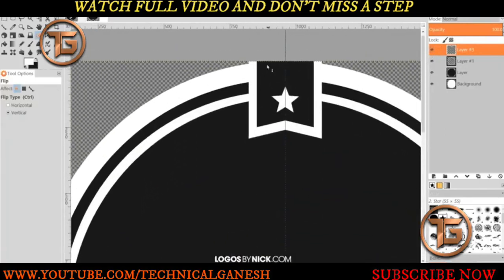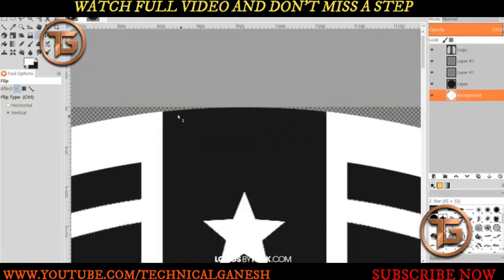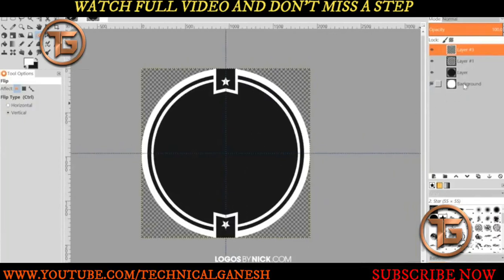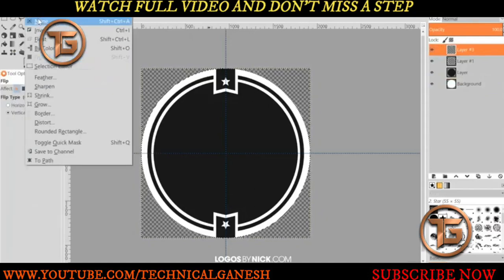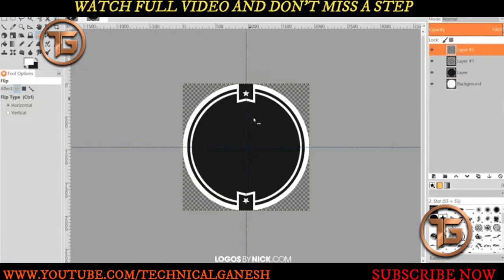And the final step for this segment right here would be to cut out this area that's protruding outside of the circle, because if you notice on the original logo, it's confined within the circle there. So in order to do that, let me zoom out. What I'm going to do is I'm going to click on our original layer down here, this white circle, the background layer, and I'll right-click that and go to Alpha to Selection, so it creates a selection going around that circle. And then I'll go to Select, Invert, and then I'll click on this layer up here, and then just press Delete on the keyboard. Or if you're using Mac, like I said, just go to Edit, Clear, then select None. If we zoom in, we see it got rid of that area that was protruding out from the circle.